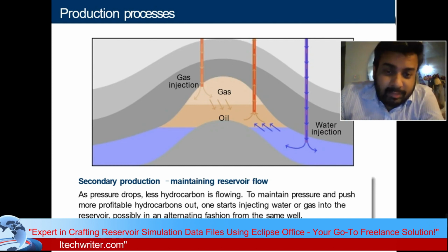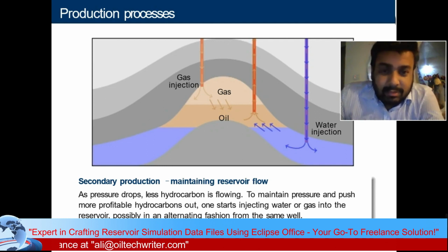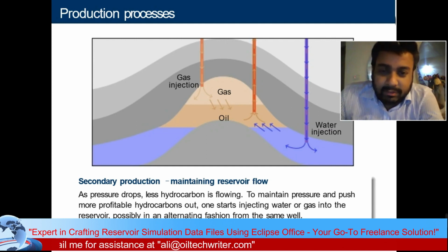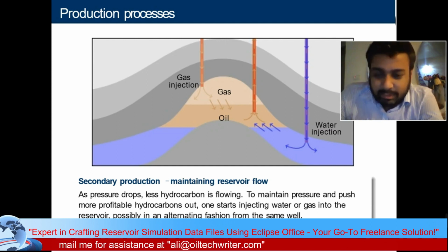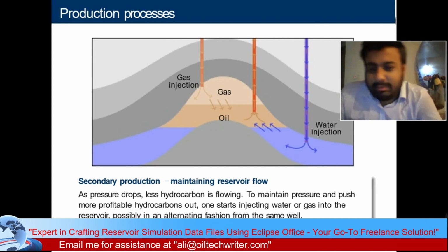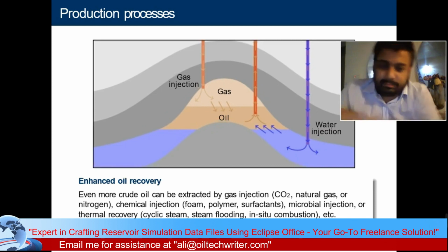And fortunately, in the Kurdistan region, our main reservoirs are still on primary production. We don't need any secondary process right now. As we have visited Khurmala, or Gazprom, or Dana Gas, their pressures are very, very good. For example, in Khurmala, the pressure was 7,000 psi and onwards. So they don't need any pressure maintenance right now, which is good for the Kurdistan region so far.